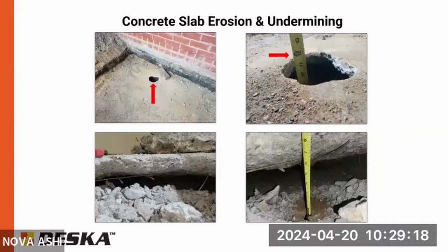We always recommend polyurethane. It's much lighter. You get a lot of pressure on that soil below. With mud jacking, if you have a 4-inch slab and then there's an 8-inch void below it, you've just tripled the weight of the slab on questionable soil. So the polyurethane is very light. Just a better product. Also, to install the polyurethane, you're drilling small, about 5/8 inch holes in the slab. Mud jacking, usually it's at least 1 inch or 2.